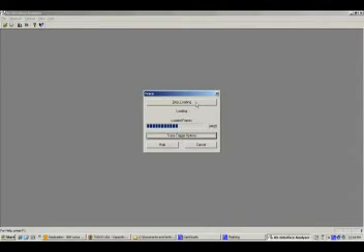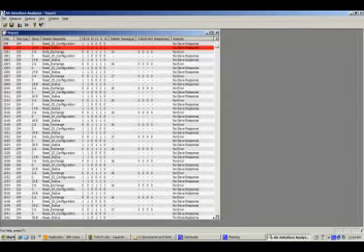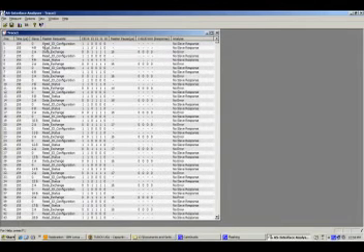If we hit the stop loading here, we'll see that it will actually pull up a timestamp of all the messages that have occurred during that period of time and the status of those type of messages, including the node number or slave address of those nodes. In this case, I only have one node on my network, and that's address 2 on this configuration here.